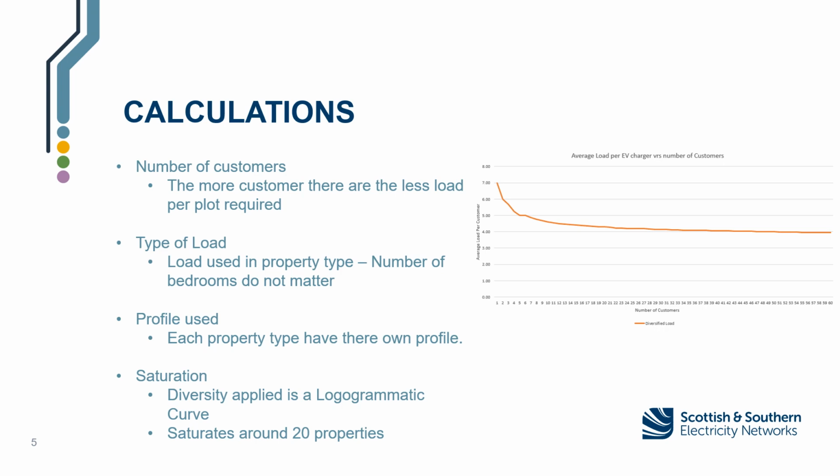We know people have electric showers, but not every electric shower has a heating element as such, so we can't really add that to our network models, and therefore we don't add it to our demand calculation. But those demands will add to the maximum demand of the property, and the calculator separates these two out to give you the maximum demand of your property and also the after diversity.